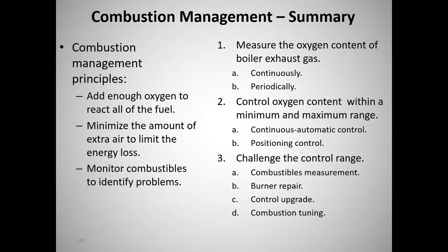So to get into testing on larger boilers, you need multiple sampling ports, or you buy sampling probes that you can move across and that are long enough that you can go across the whole duct. You can measure it here, here, here, here, here, and average it or get some kind of an idea. Make sure that the reading you're getting is really indicative of what's going on, because you can have all kinds of weird flow profiles coming out of the boiler.